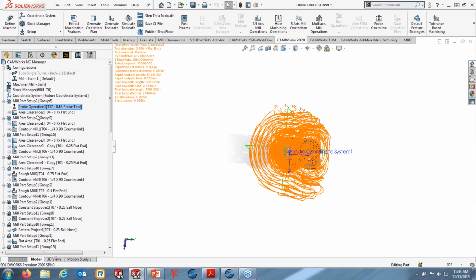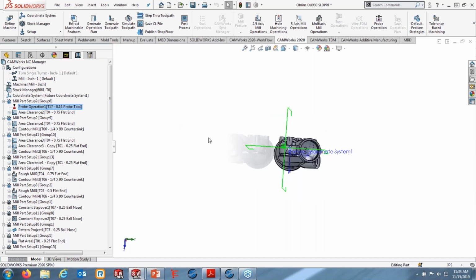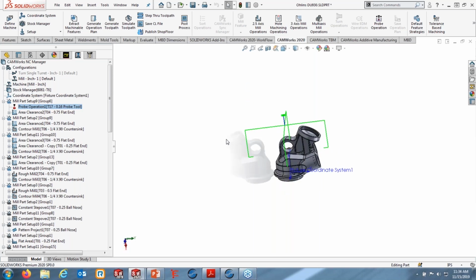But I was thinking about this and I was like, well, what else can we use it for? Maybe you're doing in-process inspection and things like that. There's obviously some people question whether you can rely on the machine that cut the part to measure it also, but essentially if you want just an idea whilst it's in the machine and it's jigged up and in its fixture and ready to go, you might want to go and look at probing a bore, for instance, over here. And I was like, well, how's the operator going to know exactly what size that boring operation is going to be?